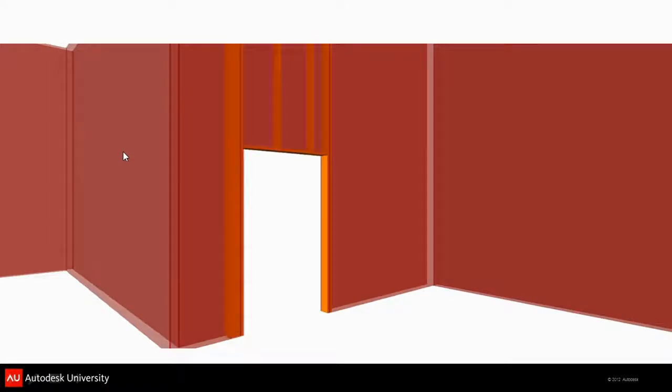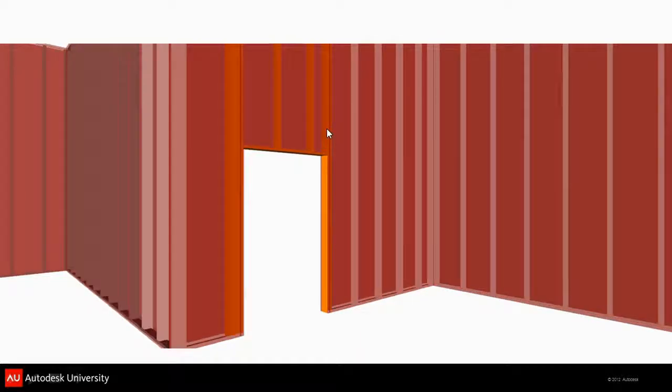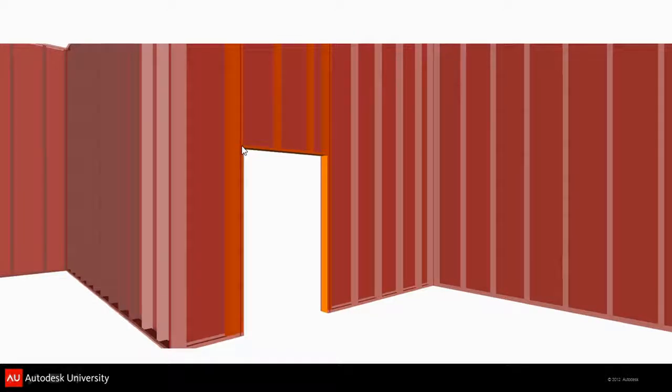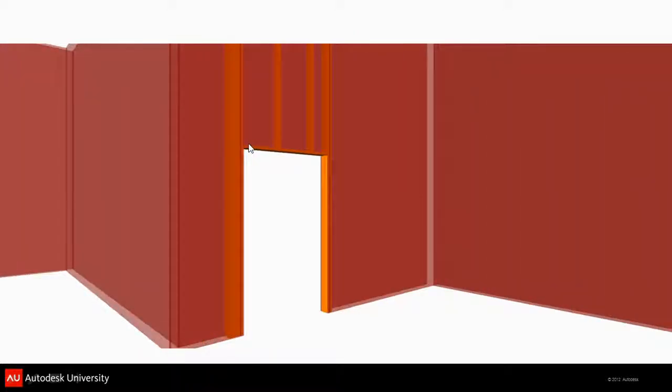If you're looking at penetrations through walls, you've got jamb conditions that you want to look at. You might need those jambs in light gauge metal studs that are hard to relocate over ribbon windows, doorways, and large openings. Those have to be engineered. They're typically double layered, and you couldn't easily cut through them without causing trouble for other people. But you don't need every stud modeled. You could just use a lightweight model. These would be important things to dialogue.